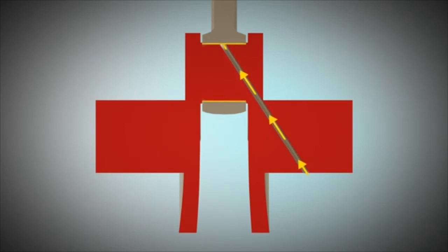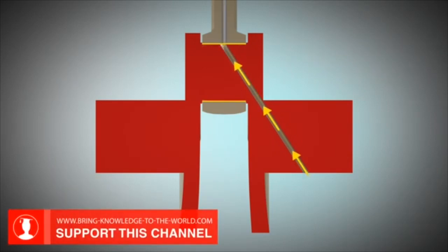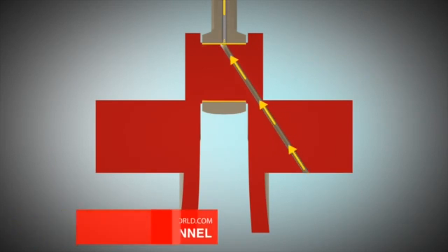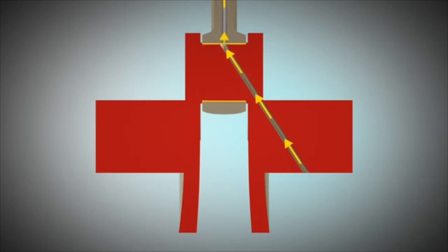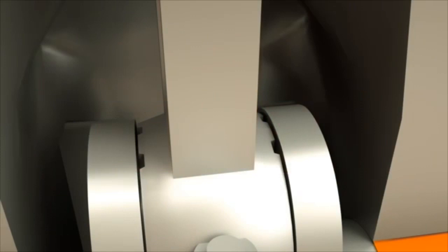In diesel engines, the connecting rod can also have an oil gallery to use the oil for cooling and lubricating the piston and the piston pin. For gasoline engines, on the other hand, the oil, which splashes out of the sides of the bearing, is used to cool and lubricate the piston, pin, and cylinder. Holes can also help to transport the oil to the desired parts and spots.